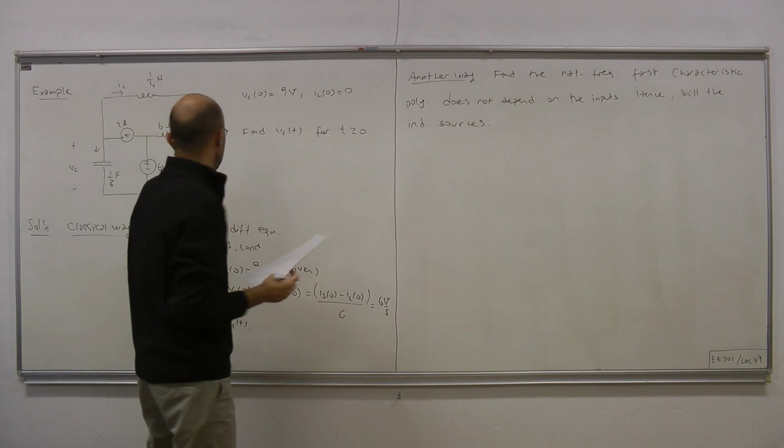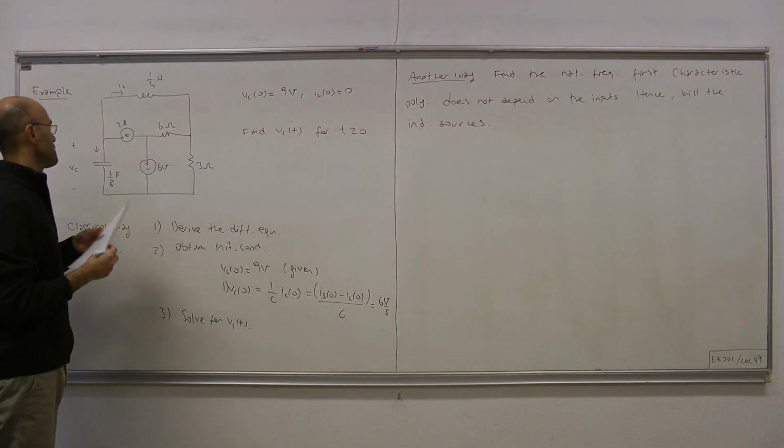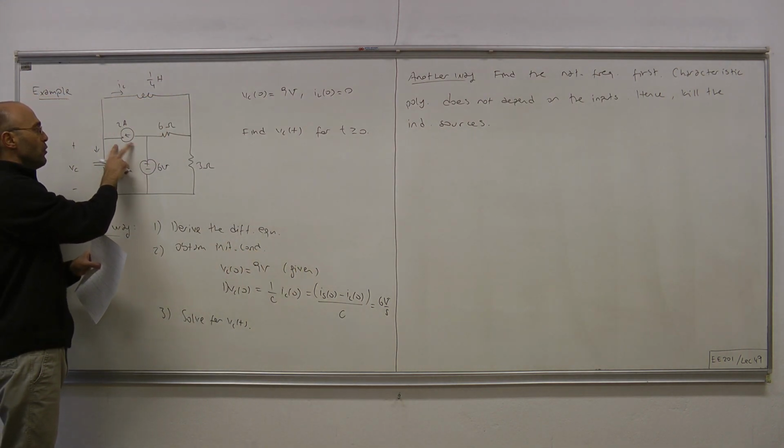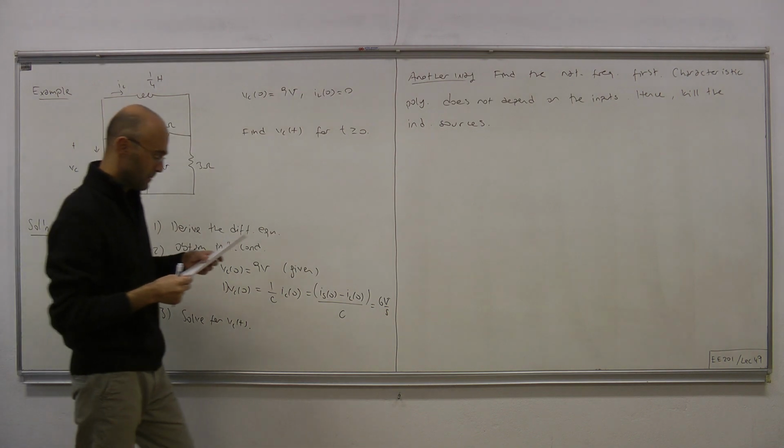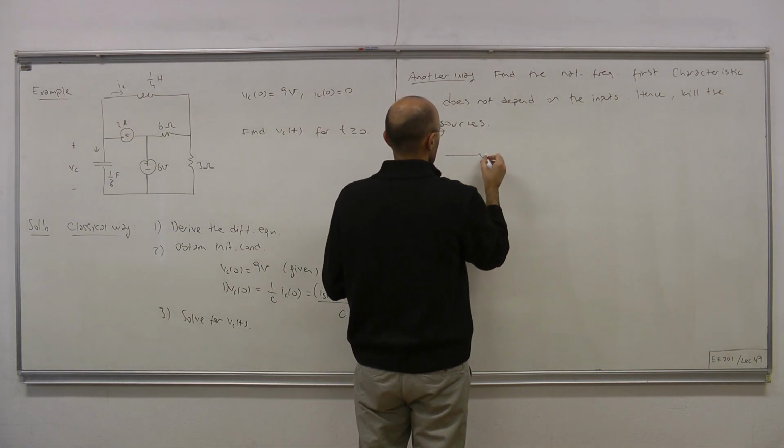Okay. Now, if we kill these two sources, replacing this guy with an open circuit and this guy with a short circuit, this is what we have.